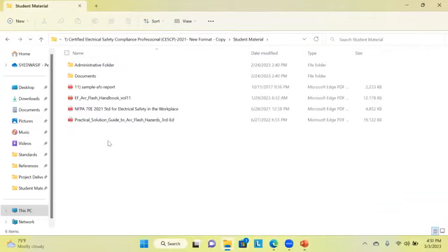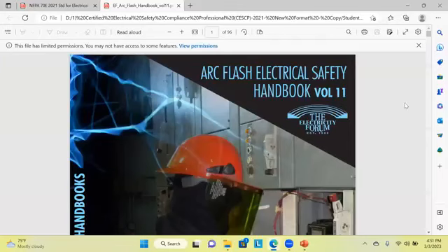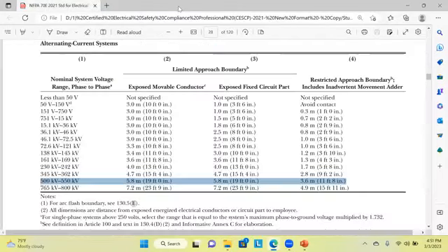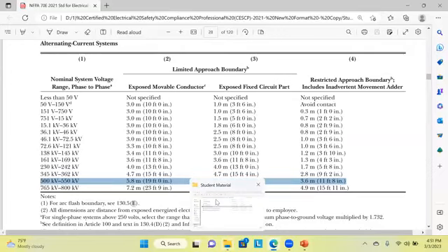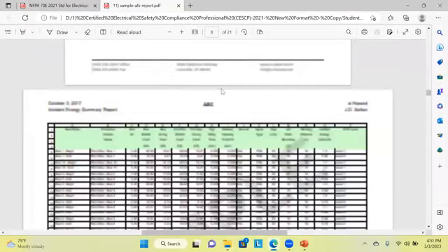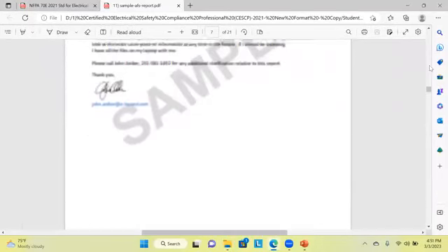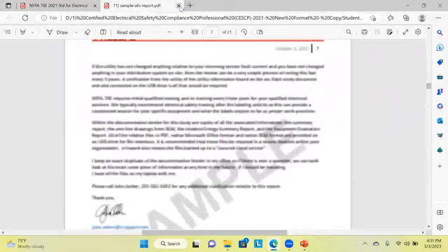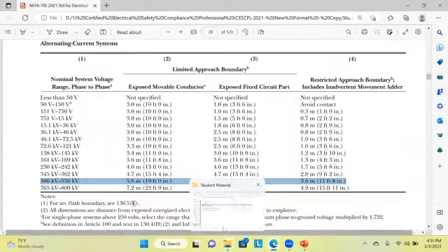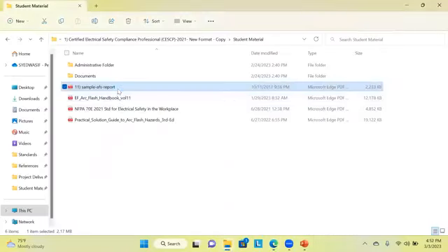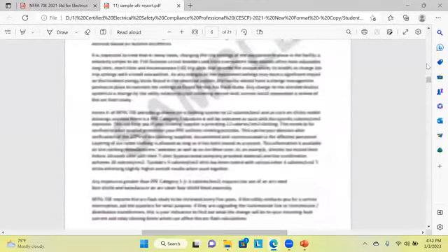Sir, for device clearance times, will the relay work or not? Yeah, both: the complete system from relay to the switchgear, in order to open and clear the fault. For example, the relay has worked and given the signal, but the switchgear has stuck due to poor operation or mal-operation. So the ultimate target of clearing the fault is not achieved.